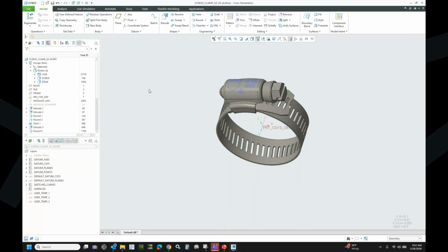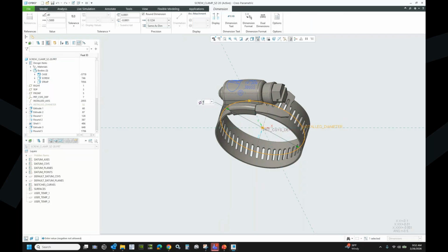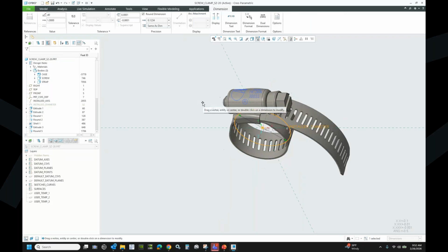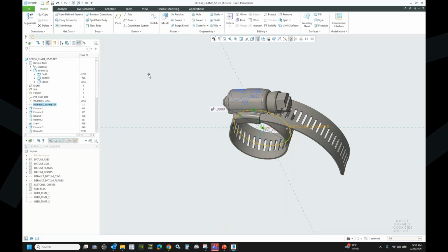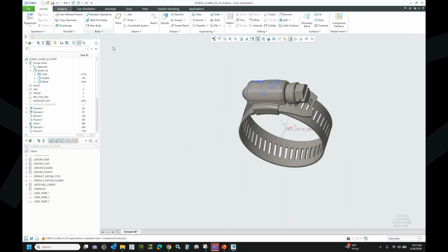Really what's driving this model when I change this diameter, right? If I say, well, I want to make that be 1, look what happens. That strap actually keeps extending. So how that works in this case is that it uses what's called a perimeter dimension in the context of the sketch. And it also uses a wrap, not a wrap feature, a spinal bend feature.